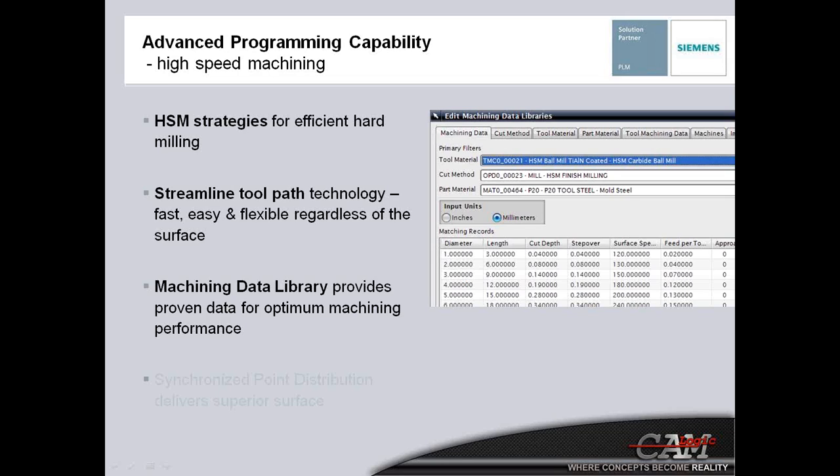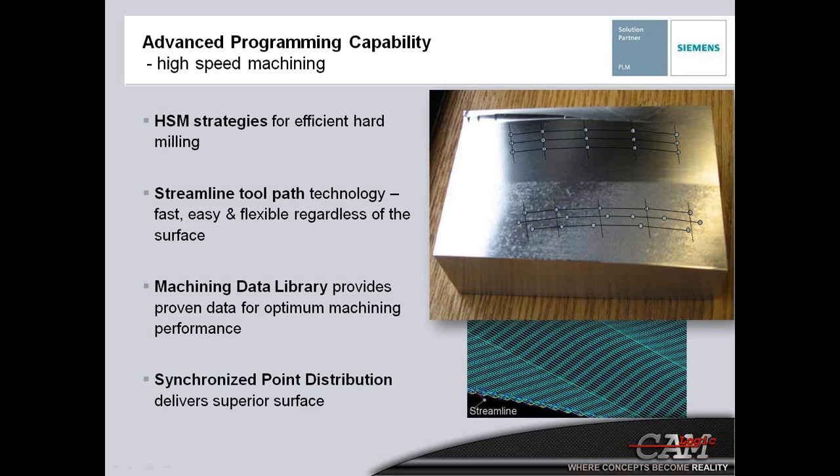They tend to take it a little bit of the step further, where it's not only going to calculate based off of your tool diameter and how many flutes and material, but it's also going to accommodate to what sort of toolpath you're providing, whether it be a finishing routine that obviously we're going to speed up our speeds and feeds for versus a roughing routine. We can take it a little bit further than what you can get out of just a standard cut data package.